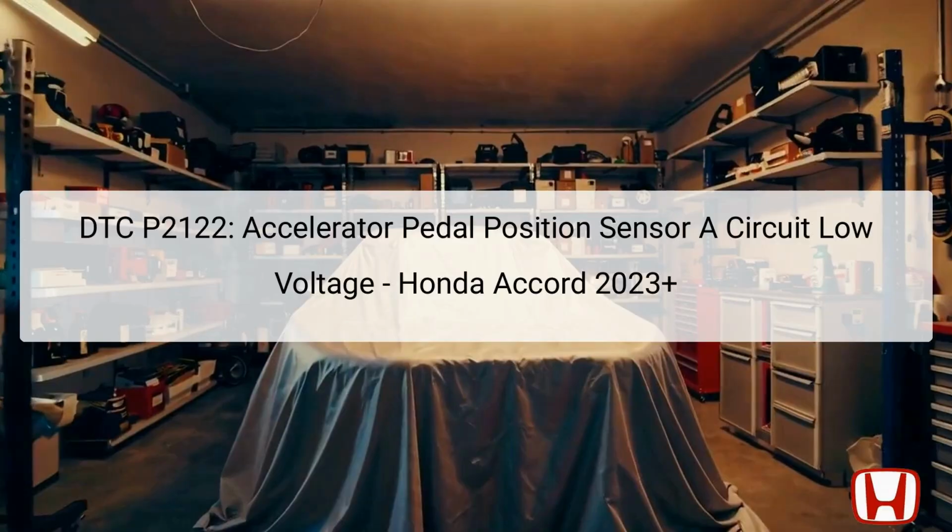The Diagnostic Trouble Code P2122 indicates an issue with the Accelerator Pedal Position (APP) Sensor A, which is integral for understanding throttle input. In this instance, it suggests that the APP sensor's output voltage is lower than a specified threshold, thereby signaling an abnormality detected by the Powertrain Control Module, PCM.